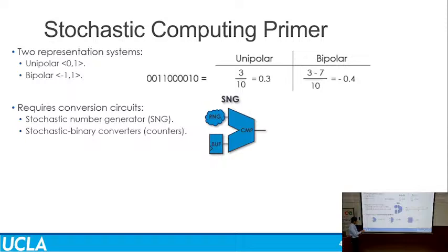And that is not very useful because you're trying to do very, very long dot products in the case of machine learning. You could do an accurate addition, which is basically put a counter and just add them. That's also not so great because then you're losing half the benefit of stochastic computing. What we use is a modified addition, which is an OR gate, which, if you plot this out, looks like a saturating adder.